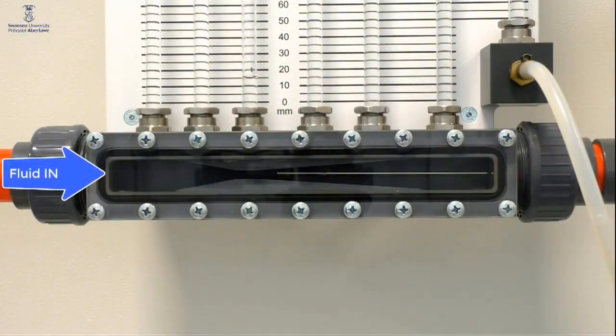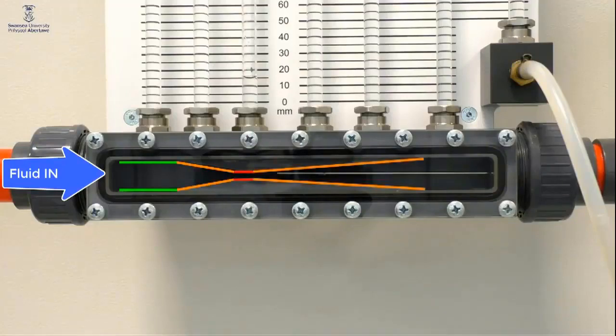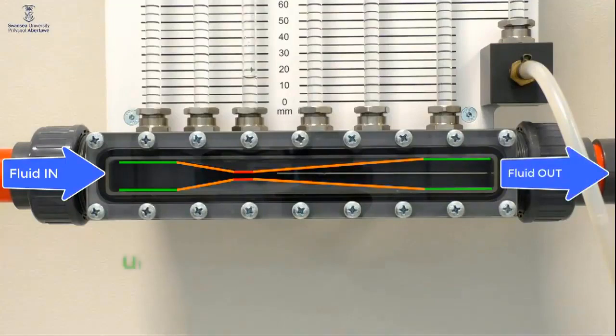A Venturi tube starts at a given cross-sectional area, converges to a smaller cross-sectional area, and then diverges back out, in this case to its original size. With a constant volume flow rate, the fluid will start at a given velocity, get faster as the tube gets smaller, and then slow down as the tube gets larger again. So according to Bernoulli's principle, as this occurs, the static pressure should decrease to a minimum where the fluid is fastest, and increase back up to its original value at the end of the tube.